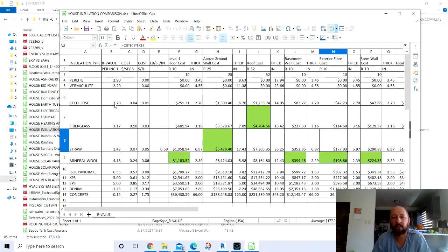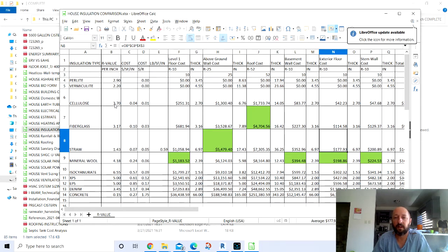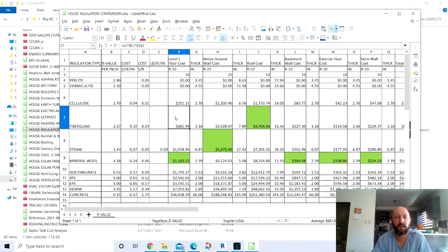And then I compared all the different R value insulations to see which is the most cost effective at insulating, and it turns out fiberglass in most situations is the most cost effective. And since it's nowadays about 50% recycled, it's also fairly environmentally friendly. I did read mixed concerns about health effects, but the general consensus was that there were no adverse health effects. So it looks like fiberglass is probably your most environmentally friendly and cost-effective solution.